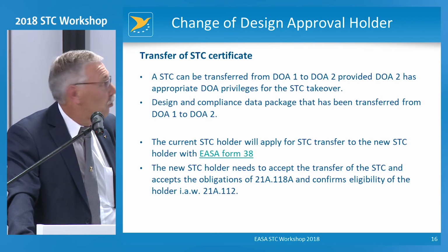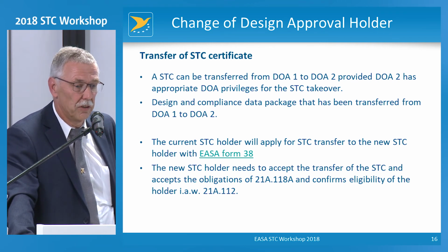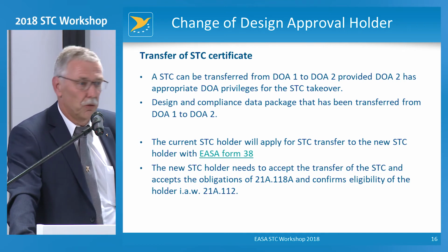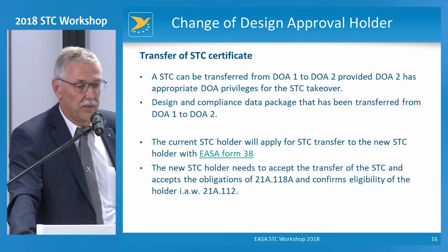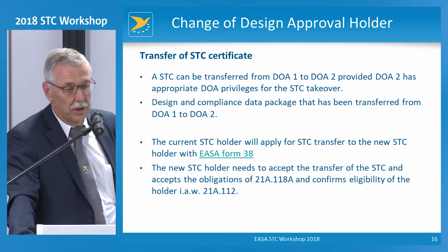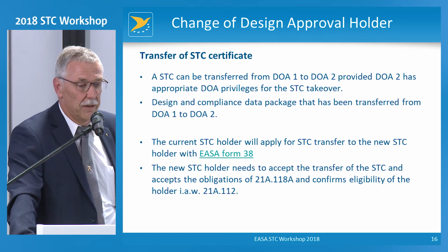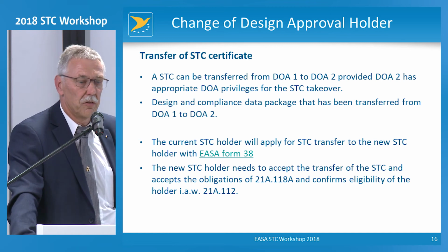The last two slides that I have: the first is for the transfer of STC certificates. Most people may know, and if not, this is a help, that an STC can be transferred from one DOA to another DOA, from one company to another company, if the compliance data package and all the information is transferred.